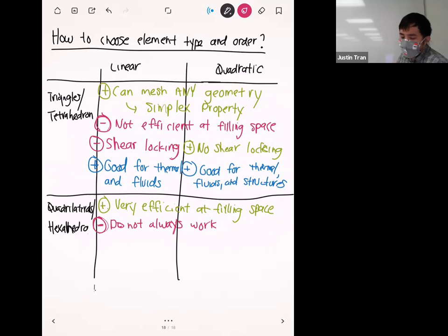Because I'll tell you, from the other side, I did a little bit of development on finite element code myself. It was really difficult to find open source packages that do a hexahedral mesh. And so we're using it in ANSYS as if it's just kind of standard, but it is really something special that ANSYS has that a lot of codes don't actually have. And so most codes use tetrahedron just because they don't have the capabilities to mesh hexahedron as well.